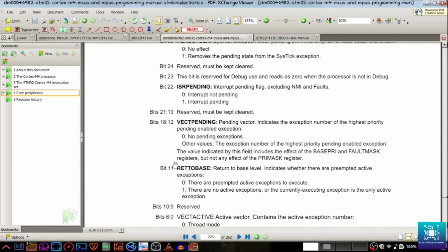We will be using the pri mask register in our application when we disable and enable interrupts, when we are doing some configuration of maybe the PLL or the system tick timer and so on. So this register is going to be used. We will not look into this particular bit field, but pri mask is going to be used. So just for your information.